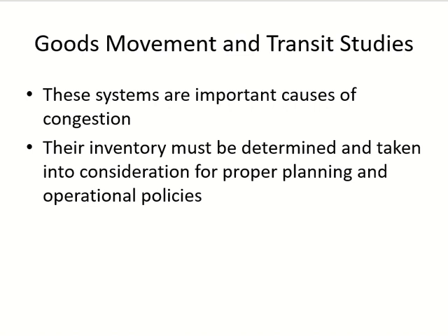If you keep the number of vehicles the same, but you increase the percentage of heavy vehicles, the traffic situation will completely change. So I have 1,000 vehicles now, after 1 hour still 1,000 vehicles. But now the number of heavy vehicles has increased from 4% to 10%. So you will see the complete difference in the traffic situation. You don't feel it, but you will often see it during the morning times because there are lots of buses going and coming.